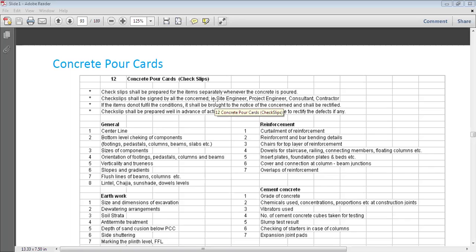The front margin you have to keep is around 3 to 5 meters. That will depend on your particular area, but at least 3 to 5 meter distance you need to keep. Side margin, minimum 1 meter distance you have to keep on both sides. And back margin, that is the rear end margin, minimum 1 to 2 meter distance you have to keep. That space is utilized for parking and the free passage, free travel of the client who is going to live over there. That is totally reserved for that particular purpose.